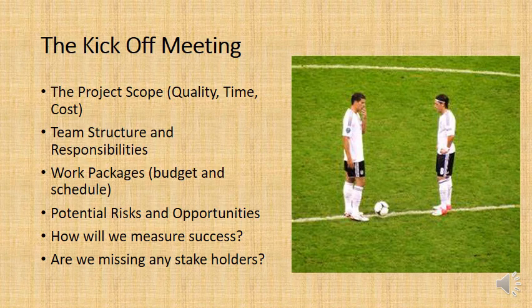So with the example of the dam project, the mechanical engineers could be talking about a certain type of new turbine, and I can speak up, yes, but with that type of turbine, even though it works more efficiently, it will create more eddy currents on the concrete draft tube and the spiral case, and it's going to wear it out quicker. And we can actually balance things out for our various components to achieve the project scope.